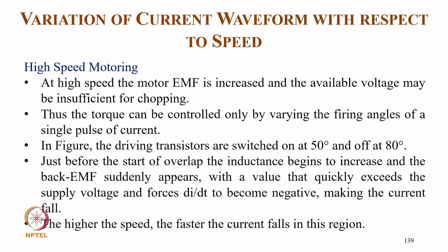EMF is increased and the available voltage may be insufficient for chopping, and thus the torque can be controlled only by varying the firing angle of the single pulse of current. And in the figure, the driving transistors are switched on at 50 degrees and off at 80 degrees.